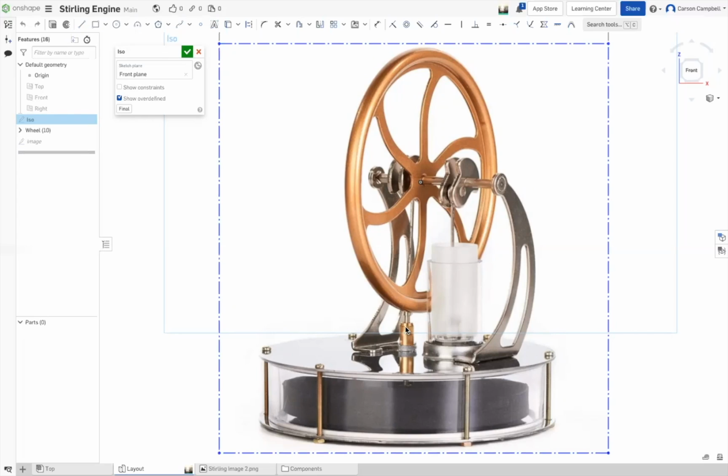So it'd be really convenient if everything's scaled together. So, this is a real fundamental question that we have to ask. Are we going to put everything inside of a part studio, or are we going to use multiple part studios? And right now we're answering that question by, I want to change something in one location, I want it to all update. And if that's what you're trying to do, then you want to do it all inside of a part studio. This is simple.